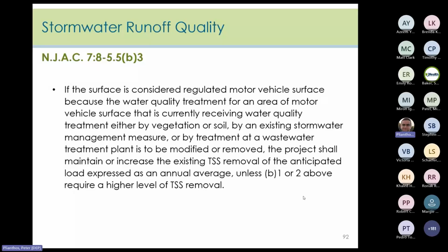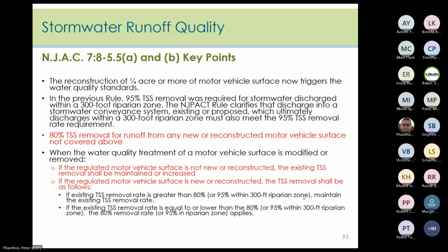If modifying or removing water quality treatment for a motor vehicle surface, the project must maintain or increase existing total suspended solids, or TSS, removal unless there is a higher TSS removal that's required by N.J.A.C. 7:8-5.5(b)1 or 2. Overall, for N.J.A.C. 7:8-5.5(a) and (b), these are the key points. Many of the points I've made in the last few slides are emphasized here.